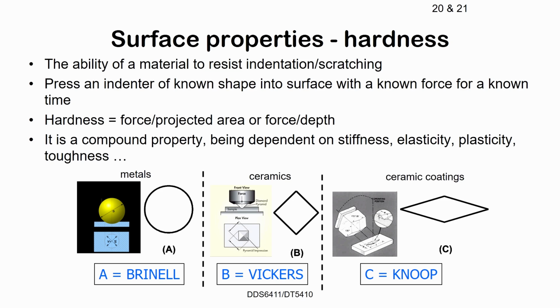So usually, if you're measuring metals, you use the so-called Brinell indenter. It's basically a sphere. Or if you want to measure something more brittle, then you use either Vickers or Knoop. For something that cracks easily, the Knoop is better than the Vickers, because you can limit the amount of fracture to a smaller extent. Because any fracture will skew the measurement of the projected area.